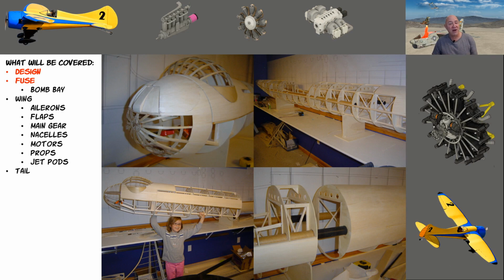It was crazy how light balsa wood is if you know how to build with it, and use some carbon fiber strategically in the right places. When it was taken into the garage and finally assembled together, the tubing in there was very thin wall carbon fiber, because once I skinned the entire airplane, and actually the tail here, I unskinned some of it, because once it's in my garage, I wanted that skin to overlap that joint. I hadn't thought about that when I was doing the original.